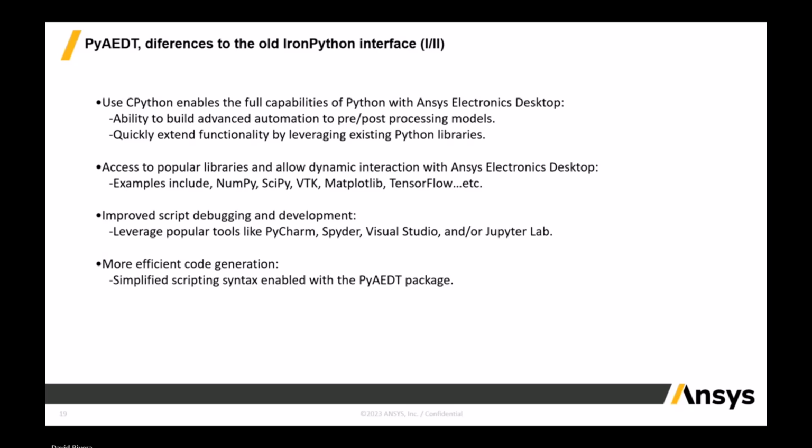With PyAEDT it is now possible. Apart from that, the syntax is much more readable and much easier to understand. If you compare code between PyAEDT and the AEDT API that I will show you in the next slide, you will see how easy it is to understand the syntax. PyAEDT also allows easy access to any IDE, the software that you use for programming. Before, with IronPython it was almost impossible to use any IDE like PyCharm or Visual Studio, but with PyAEDT it's quite easy to just create a Python environment and write your code.